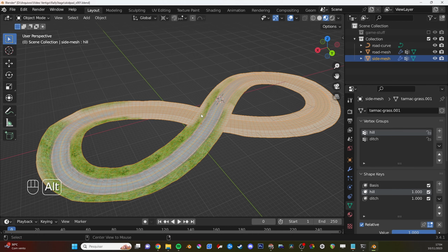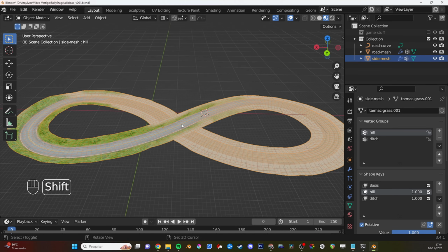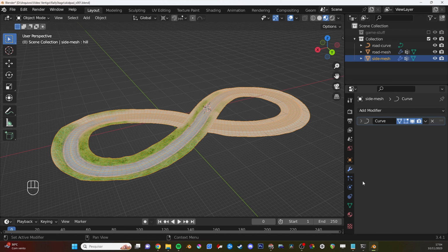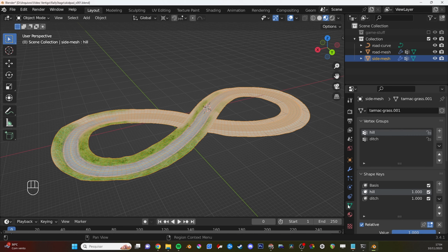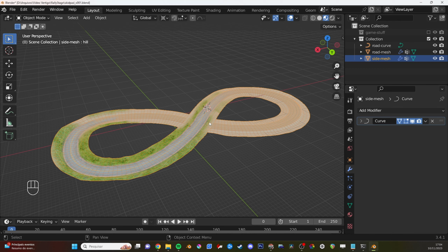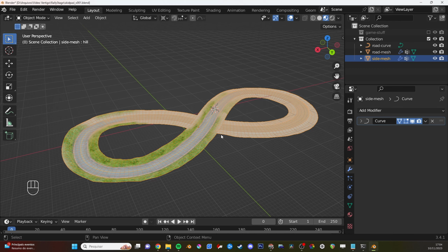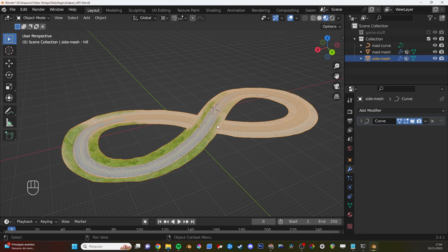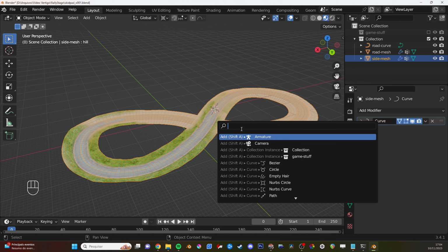So in this case, you're gonna have to use another strategy. It's actually pretty simple. There is a way that you can go and apply lots of modifiers at once on a mesh, and this will solve our problem here with the modifiers. So here, actually, I'm gonna need to press F3. If you haven't changed any configuration of Blender, F3 will by default open the search bar, which is very useful and handy.